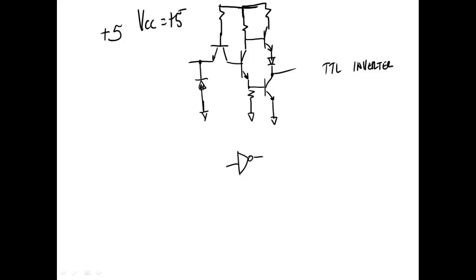Now, there are limitations on this, but you have to understand it's impossible to get exactly plus 5 volts. Even with regulators, there's no such thing as a perfect voltage regulator. So that means when you load these power supplies, the voltage goes down a little bit. When you unload them, they go up a little bit, but it's not very much.